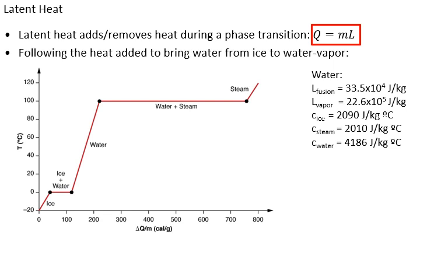If we take a look at how much heat is required per unit mass to raise an object by a given temperature, here we're looking at water, you get the following curve. In the linear portion, the part that has some slope, this is our Q = mcΔT, the formula we were talking about previously. Then in your phase change, this is the heat you're paying to do the phase change. To go from ice to water, you need to add heat, and what you're absorbing in this case is the mass of the water times the latent heat of fusion. Then you can continue to heat the water to raise its temperature. This is Q = mcΔT.